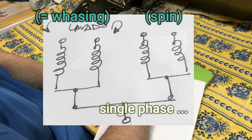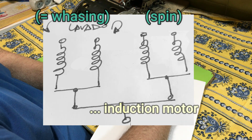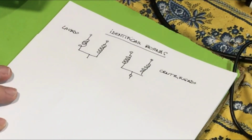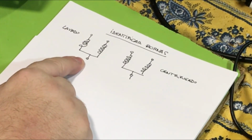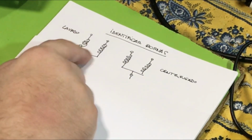In this case, we have at minimum 5 terminals because we have 2 windings for washing, 2 windings for spin, and then the common point of the windings can be separated. So then in this case we have 6 terminals.